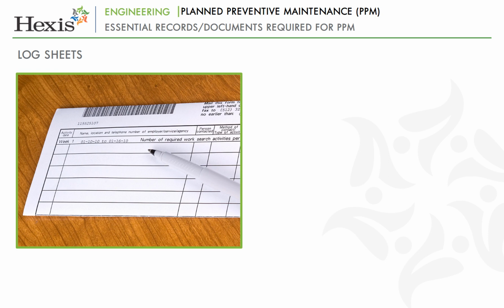It is imperative that duty staff in all sites go to all equipment and check the status of the equipment and whether they are running in accordance with the operating parameters it is designed for. Some equipment also has measurement instruments which show the parameters online. These parameters should be recorded for posterity and also as evidence of the staff having taken rounds of the facility diligently. The recorded parameters also assist in analyzing or benchmarking performance data of equipment. The parameters are recorded in a log sheet or a check sheet.